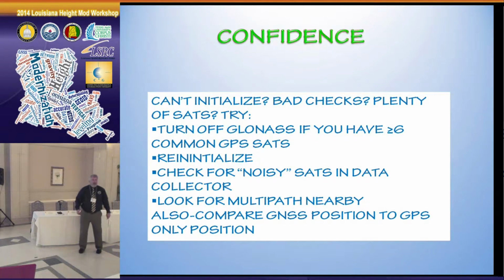Another thing too with GLONASS. GLONASS has ground monitoring stations, but they're trying to build out. But up to now, they've been all in Russia. That means when the satellite goes overhead, okay, that's it, and then it goes over the horizon. That's it, until it comes around again. The U.S. has 6 or so, well, more than that, monitoring stations. And they have at least 2 of them observing each satellite all the time. So you can have a little bit more confidence in what we have than the GLONASS system.